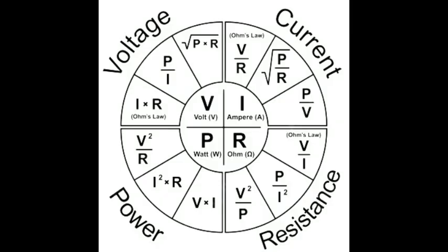So in order to insert our formula number 4, we have to be missing a resistor value. So here, I would say R total equals 1 over the value of my total resistance, which would be 2, minus 1 over 10, minus 1 over 5.